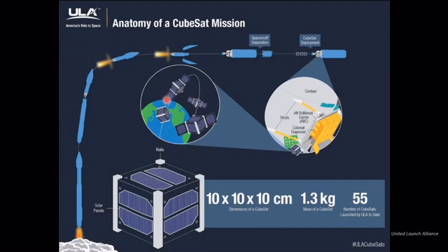Then the next task is to operate the CubeSat or the satellite itself for the mission life you design for. A typical mission life for a CubeSat is 3 years or less, but for bigger satellites, this lifetime, of course, is much bigger. Traditionally, if you design a CubeSat for 3 years, it can definitely last more than 5 years. But in order to not create junk in space, there is a standard that you have to ensure you bring the spacecraft down to the atmosphere within 15 or 25 years.